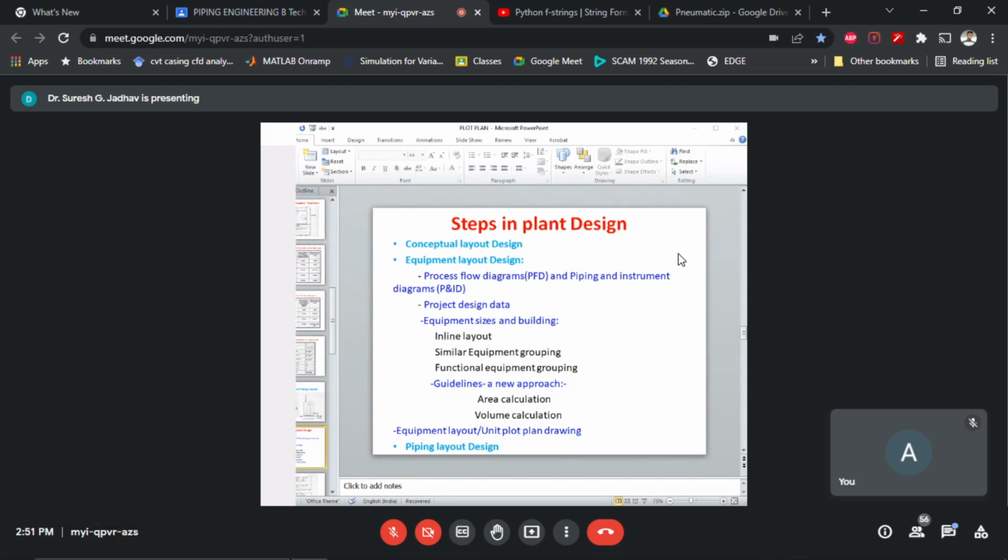They are designed to help prevent major catastrophes, especially when highly inflammable chemicals are involved. These guidelines, while useful, often include ambiguous entries such as provide spacing based on access for operation and maintenance as required and not applicable. Hence, these guidelines alone could still result in crowded plants.